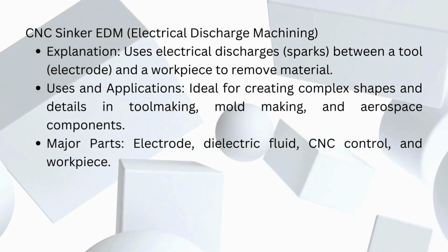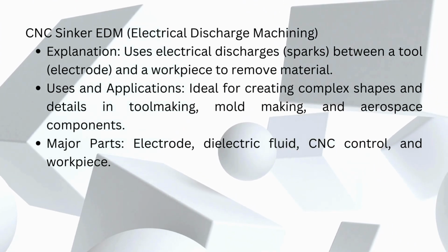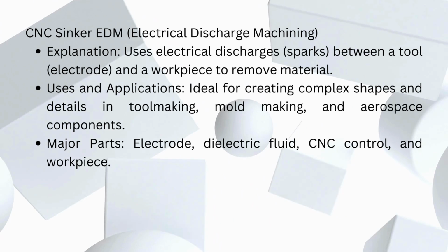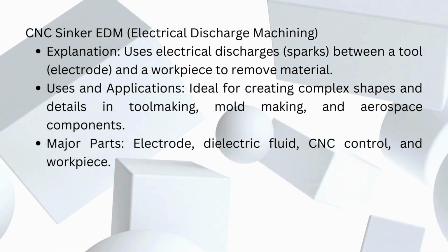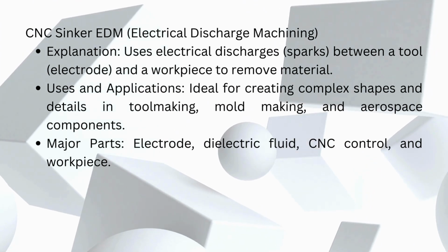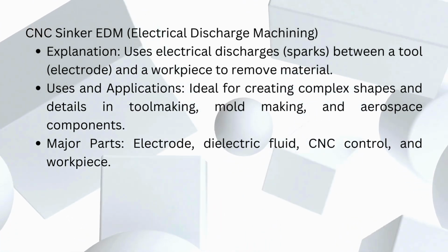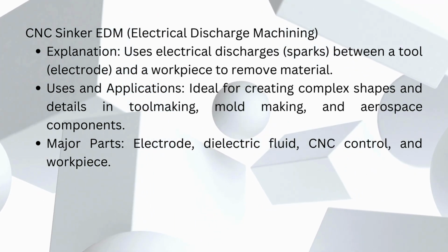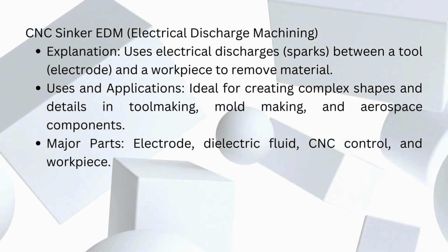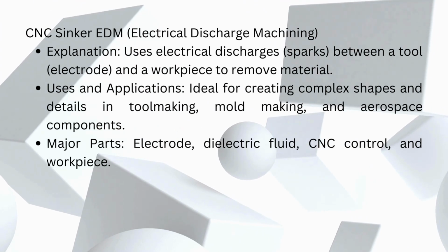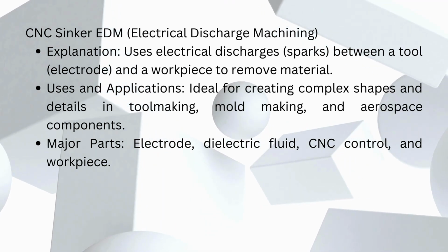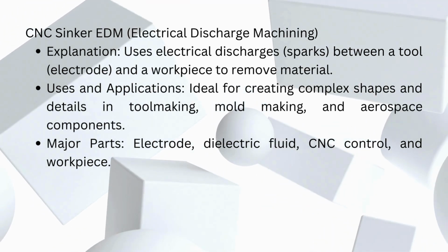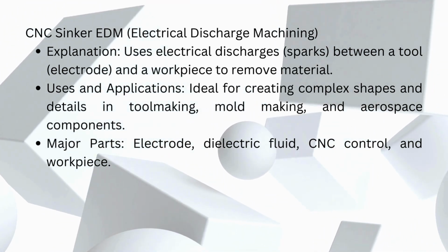CNC sinker EDM, electrical discharge machining. Explanation: uses electrical discharges, sparks, between a tool, electrode, and a workpiece to remove material. Uses and applications: ideal for creating complex shapes and details in tool making, mold making, and aerospace components. Major parts: electrode, dielectric fluid, CNC control, and workpiece.